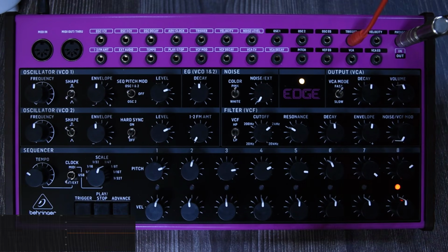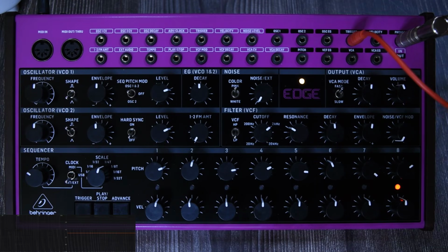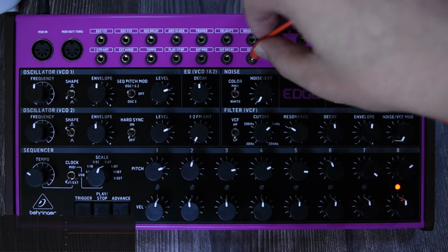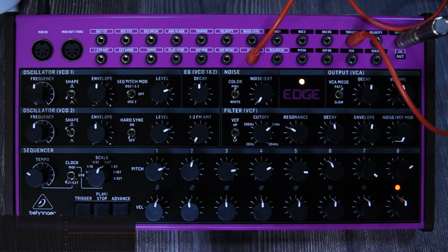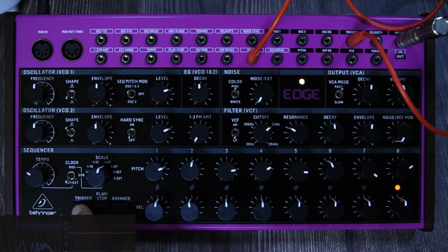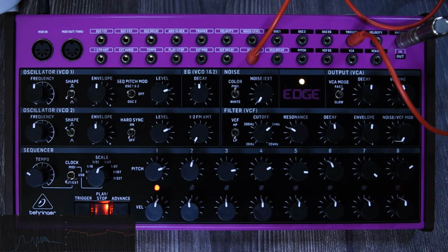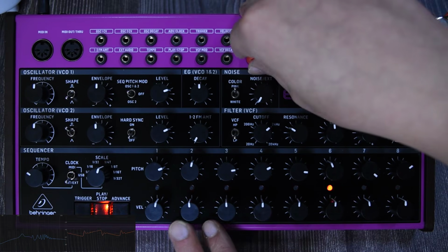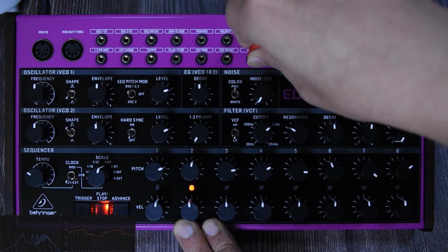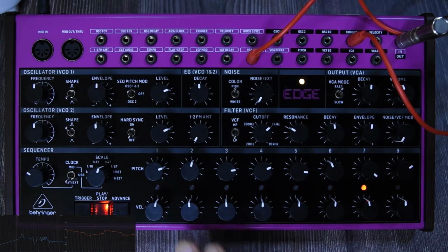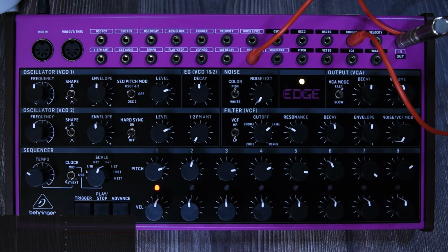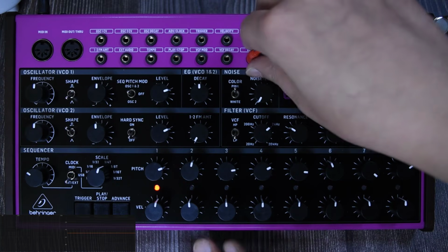So for example, if I try to use it on this synthesizer alone, I could use the trigger out to maybe go to the VCA CV in. And every time that we go right here, maybe to the trigger, we can hear a very pulsating sound. That is super sharp. If I disconnect it, we are not getting it. So what we hear is that pulse. Again, this is something that maybe is better used with a different synthesizer.